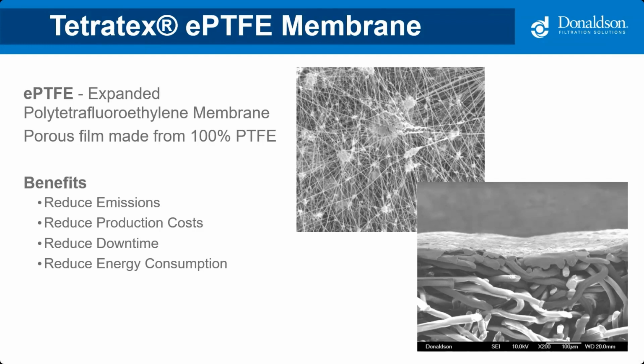Now, in the foundry industry, I'd be kind of careful with using EPTFE membrane. Make sure you're talking to your rep about the actual process, because the Achilles heel of membrane is oil. If you are using it off of your furnaces or off of your molding departments where you might have some binders or some oils coming from dirty steel that you're melting, you could run into some issues using an EPTFE membrane.